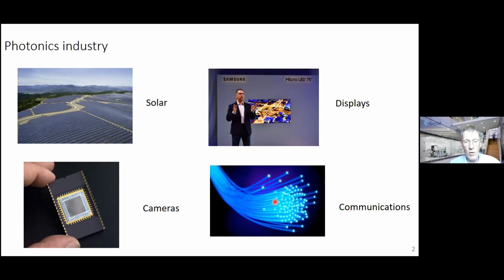So if we go to longer wavelengths, we first reach about 800 nanometers, where there's a lot of interest in communications. But optical fiber, it turns out, has the lowest loss in the 1.5 micron range. So that forced technologists to develop lasers working in that wavelength range, to make modulators to send that data, and detectors.